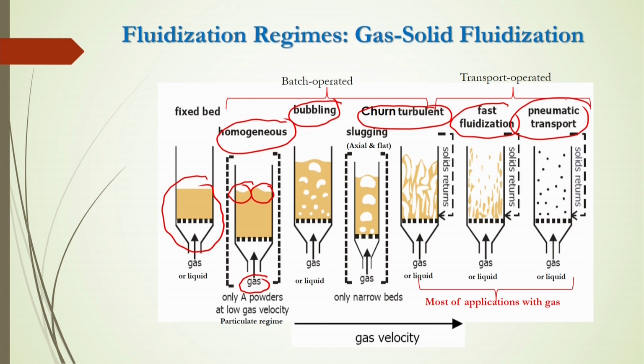There are two types of fluidization flow regimes, and all these flow regimes will change if you change the gas velocity inside the bed. But you cannot say they change only based on the gas velocity. If you fix the gas velocity and change other variables, like geometric variables, the particle diameter, or the physical properties of the system, for example using a higher density gas, then you will get different types of flow regimes also.